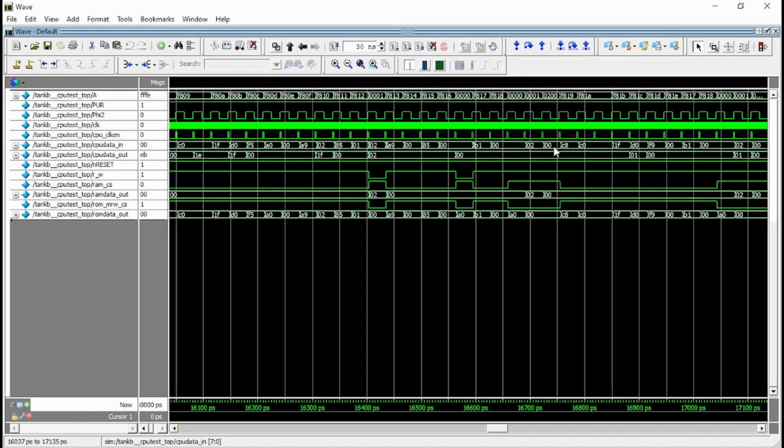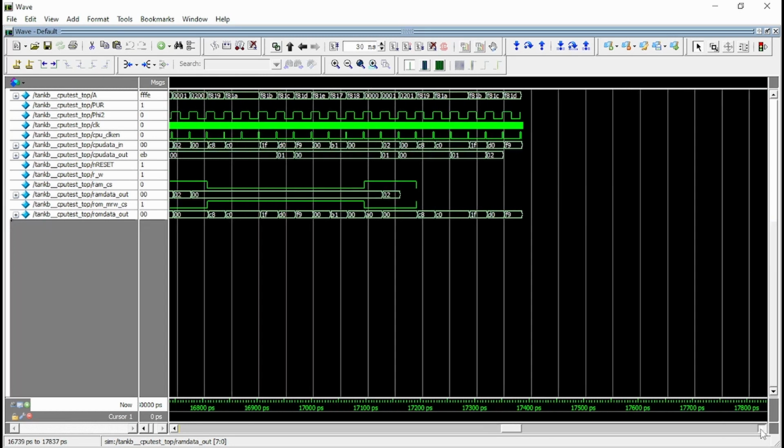So we're reading from the RAM here, RAM data out is 0, and that's going into the chip as 0. So that's what we expect at 0200. We remember that we won't get anything until we go to 0203, so we move to there.